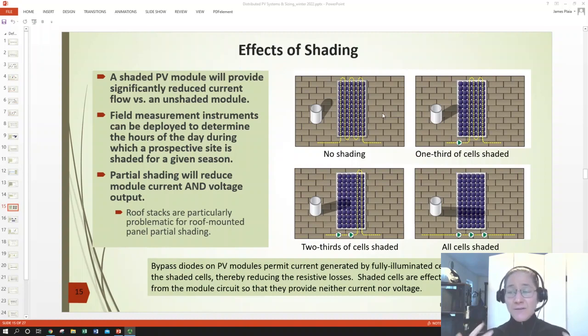Definitely, in addition to simply having fewer photons overall, remember how the cells in a module are in series? So there's a joke about series connected Christmas lights that if one goes out, they all go out because you no longer have a continuous circuit. It's not quite so bad with series connected solar cells because if they go into shade, such as we see here for these first two rows, remember everything's in series, everything's connected, they're still electrically continuous, but because they're not generating power, they're basically like a big resistor. So they're consuming power in moving the electricity generated by the other cells through them.